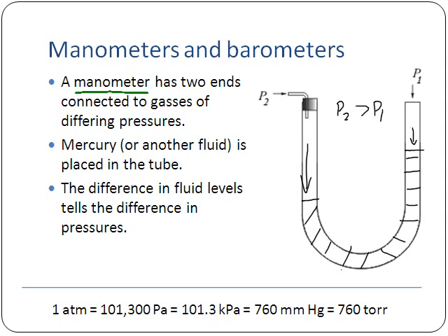How do we know exactly how much different the pressures are? Well, this comes to the issue of why we call this millimeters of mercury. Remember that we said that inside this container, we basically have mercury. So there's mercury down in here. That's the fluid that we have here. If we were to stretch this out and measure the height difference between each section, that height right there, if you measure that in millimeters and your fluid is mercury, then you are going to get a difference in what they call millimeters of mercury.